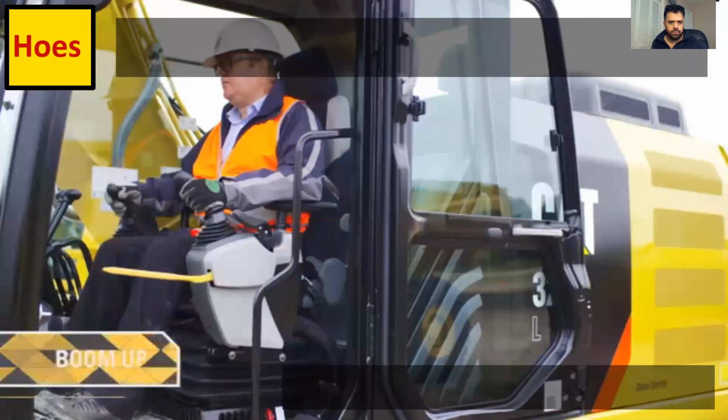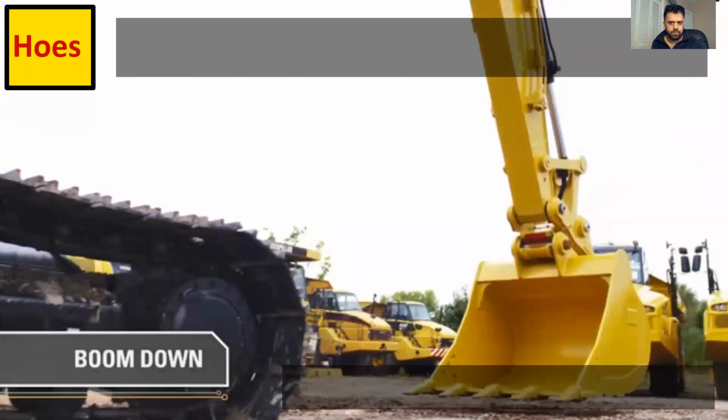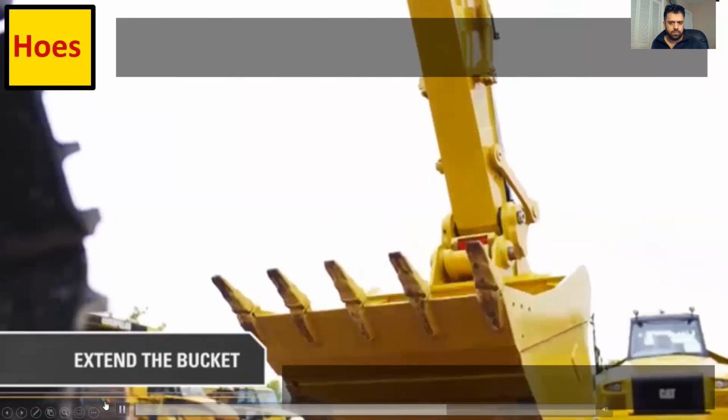Move the right joystick towards yourself to bring the boom up. Push the joystick forward to bring the boom back down. Moving the right-hand joystick to the left will scoop the bucket toward the cabin, while moving it to the right will open and extend the bucket to release the material.